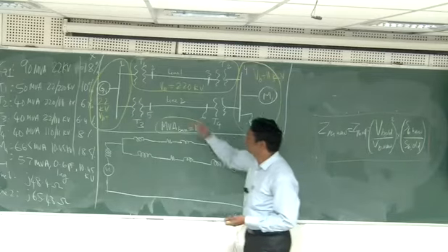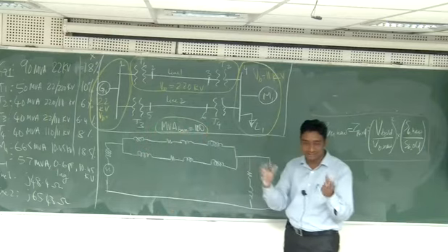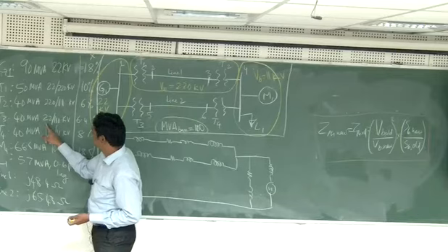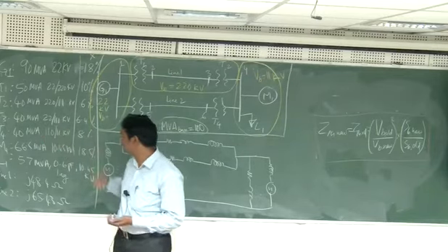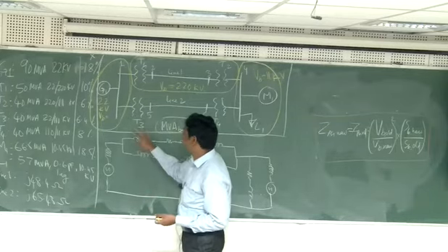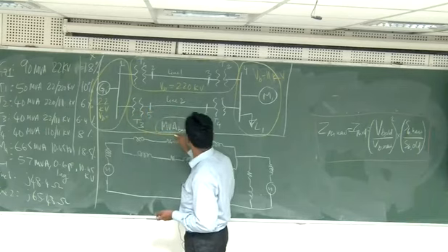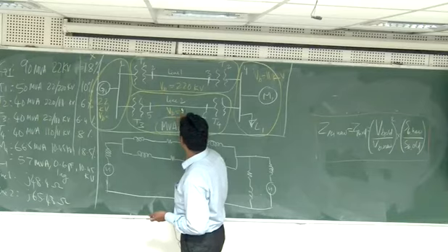Now look at line 2. Wherever there is a transformer, there will be a change in the region. So transformer T3, 220 kV by 110 kV, how much is the ratio? 2 is to 1. Therefore for this entire region I will choose V base as 110 kV.